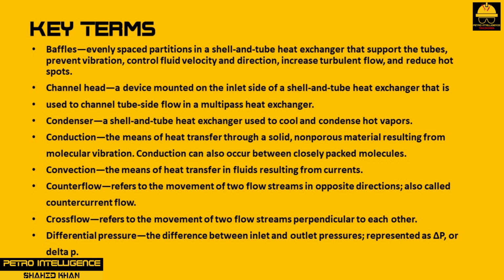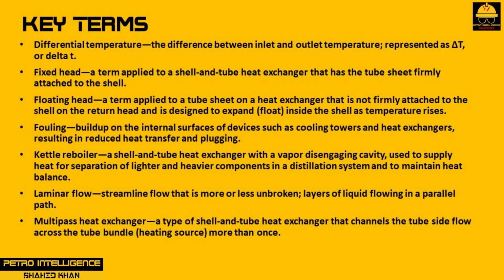Differential pressure is the difference between inlet and outlet pressures, represented as delta P. Differential temperature is the difference between inlet and outlet temperature, represented as delta T. Fixed head is a term applied to a shell and tube heat exchanger that has the tube sheet firmly attached to the shell. Floating head is a term applied to a tube sheet on a heat exchanger that is not firmly attached to the shell on the return head and is designed to expand or float inside the shell as